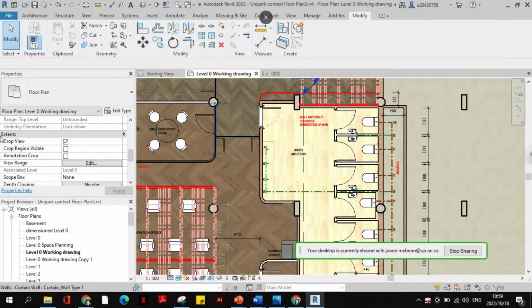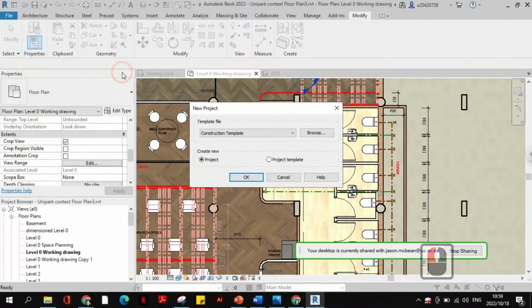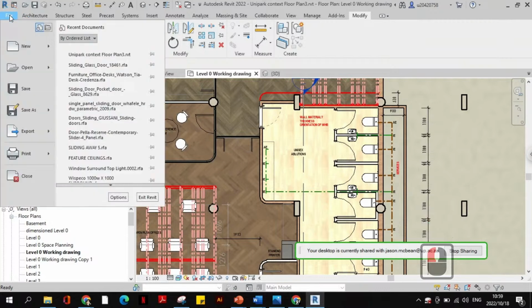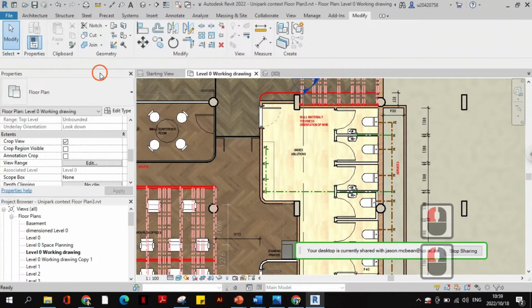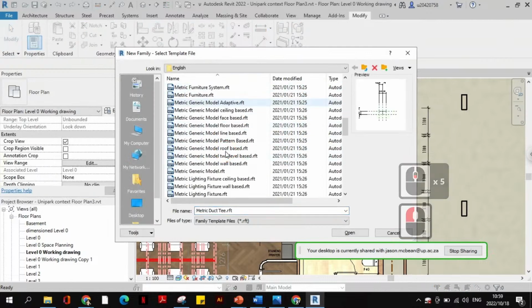Okay. So here you have to make it externally. File, new. Let's just start with embedding it in the wall, because that's probably the best option first. Yeah, let's start with this option. It's a bit tricky when you need to use them sometimes. Okay, so in Revit, file, new family. Now you must always make sure it's a metric door.